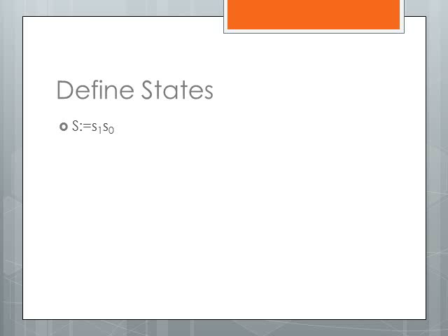Because there's no real description on each state, we're just going to give them letters. Because really, we don't have a very descriptive example here, like a traffic light or an elevator. So we're just going to give them letters. And again, this is also just because we want a simple example to go through. So we define them in order logically. A is 0, B is 1, C is 2, and our last state, D, is going to be 3. In binary, not in decimal, just to clarify.